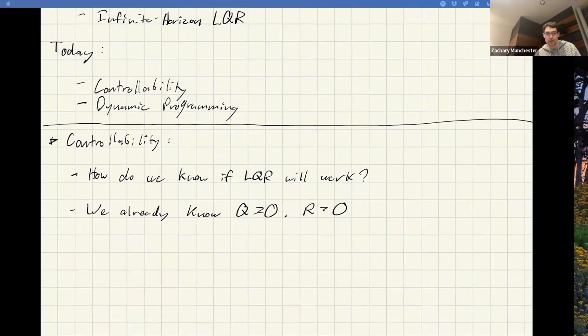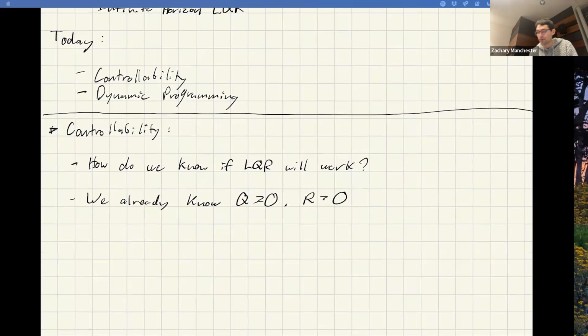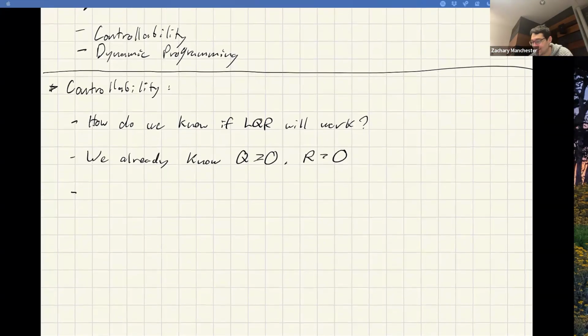Okay, so we already know this stuff. And basically, what we're going to talk about right now is a special case result specifically for LTI systems, linear time invariant systems. There's a nice clean result in that case. In the general time varying case, you can still do it, but it ends up basically being you just try solving the QP. If the QP is feasible, then it's controllable. And if the QP is infeasible, you're out of luck. So in this case there's a clean, nice result. In the more general setting, the answer is not very clean, and you just try solving the QP in practice.